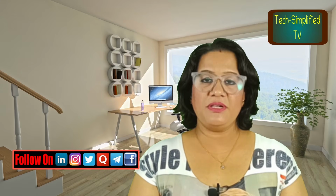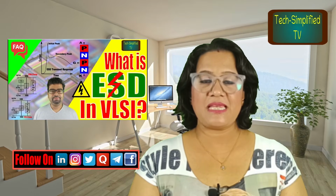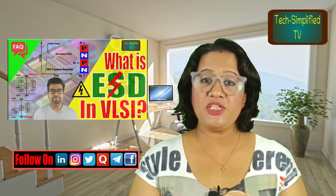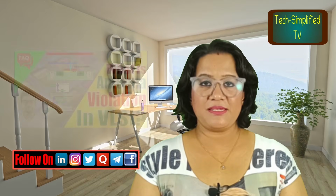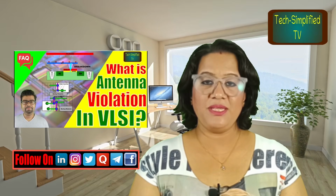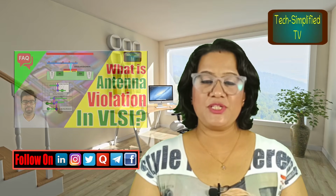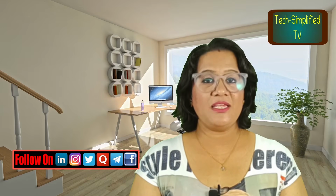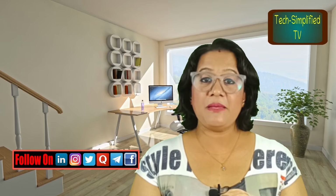We will also cover ESD, that is electrostatic discharge, where a tiny spark can destroy a whole chip, and the antenna effect, where charge buildup during the fabrication steps damages the gate oxide. Reliability is not just making circuits work, it's about making them last.